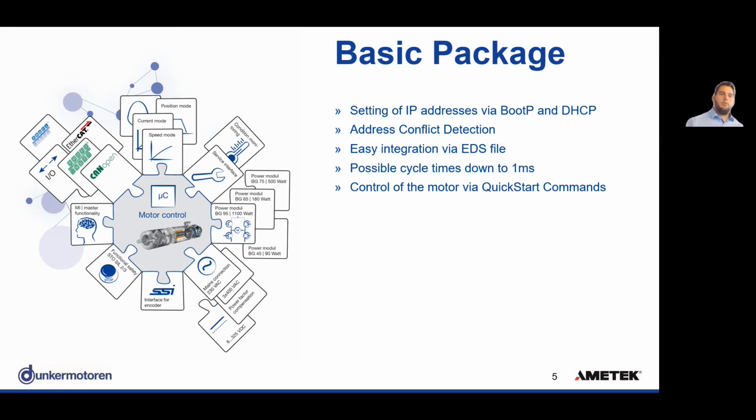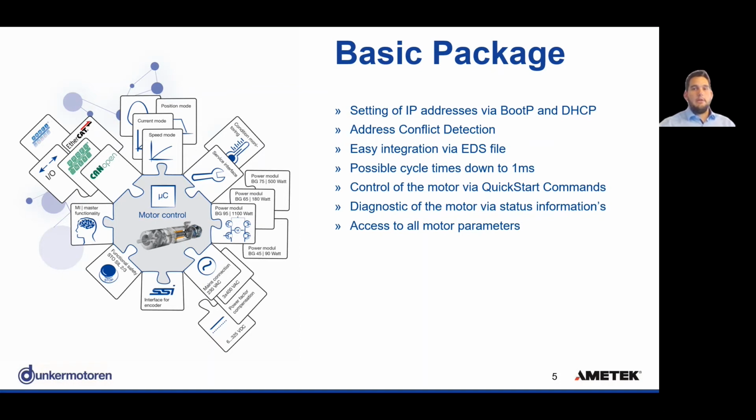If you also use other motors from us with other protocols like Open Motors, Profinet or EtherCAT motors, there's the same logic behind it and you can control the motors over all the protocols in the same way. The diagnostics of the motor is given by providing status information of the motors to the PLC, and of course you have access to all the motor parameters that are available. You can read and write them.